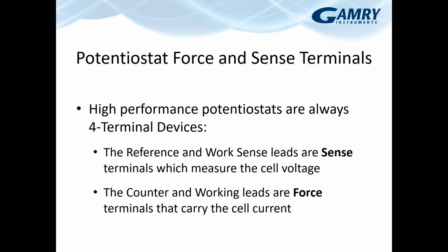Force and sense terminals. High-performance potentiostats are always 4-terminal devices. There are 2 terminals, the reference and work sense leads, that are sense terminals. Those measure cell voltage. The other 2 leads, the counter and working leads, are the force terminals, and they carry the cell current. A lot of times you will not use the term force very often, just call them the current carrying and the sensing leads.